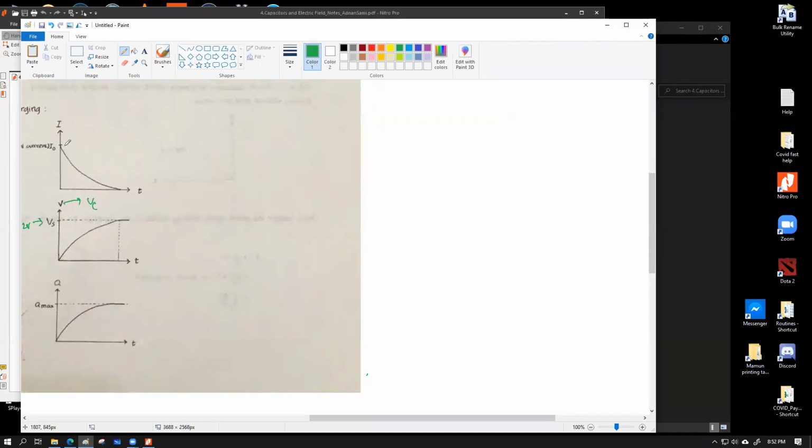So you have the highest current through the circuit at the beginning because you have a fixed resistance and the entire EMF available from your source. But as time goes by, your reverse voltage, which is the voltage across the capacitor, slowly becomes bigger and bigger. As a result, your effective EMF becomes smaller and smaller. So as current goes lower, the charging rate becomes smaller. That's why the capacitor does not charge as fast as earlier, that's why it is losing gradient, and eventually it comes to horizontal at the 12 volt value.